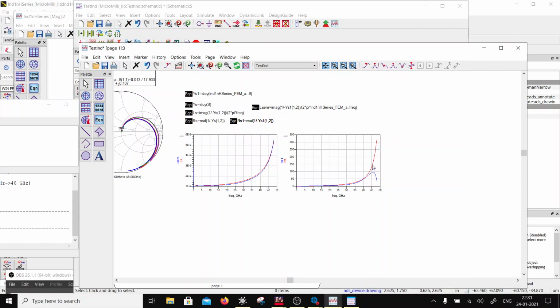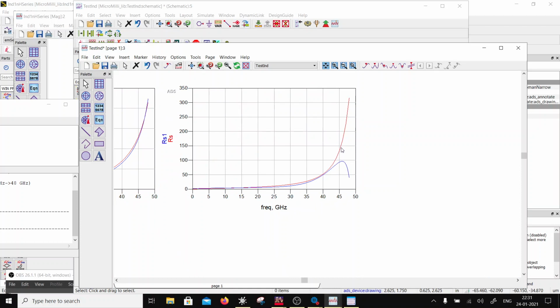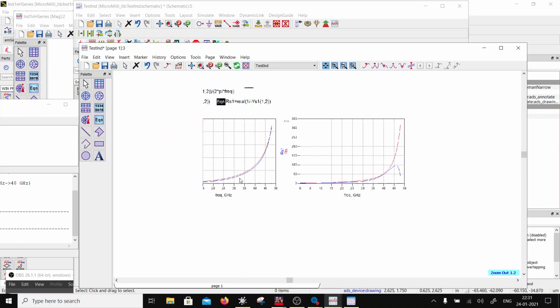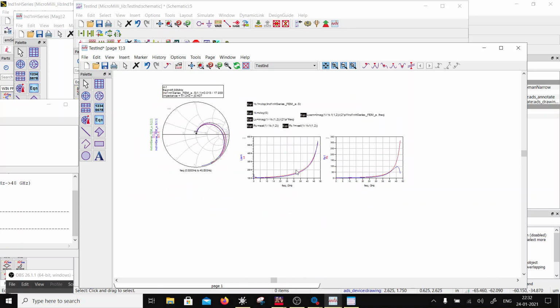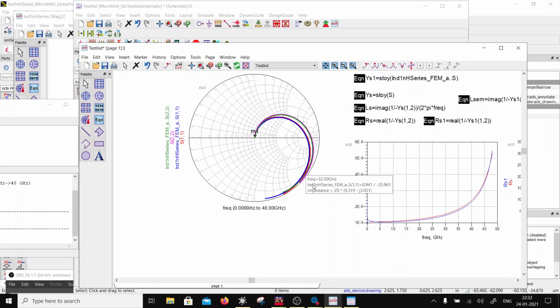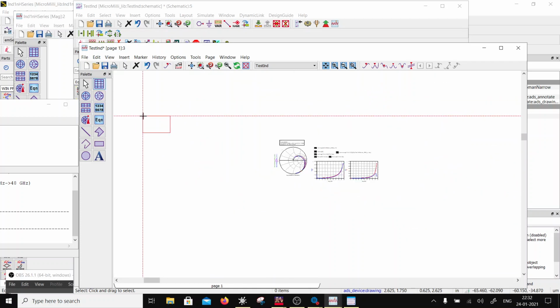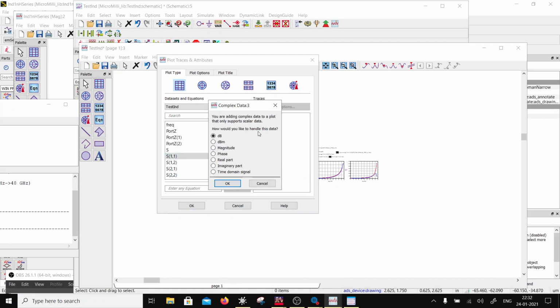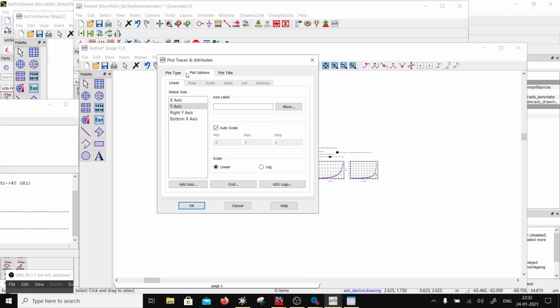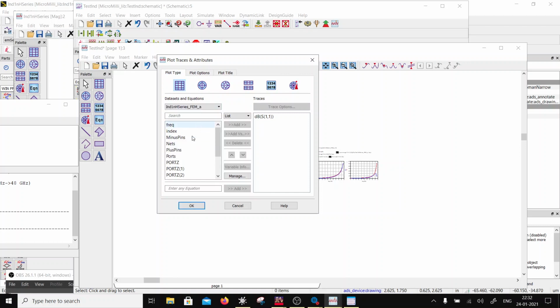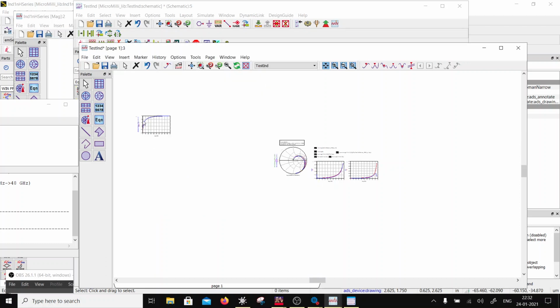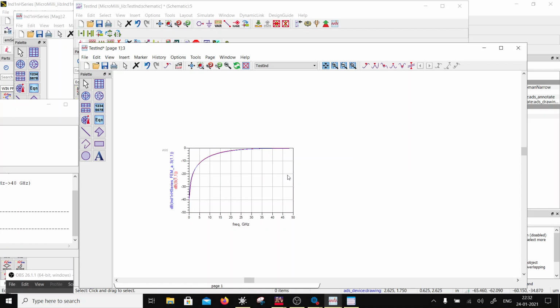Okay, so up to here it is going to 150 ohm and this is going to be 100 ohm. So there has to be a correction over here somewhere, right? There has to be a correction over here, right? So I'm going to leave it at that because I'm okay in this range where I want to model this, right? So let's look at S11 here in dB, and let's look at the S11 from the EM simulation in dB, and let's see how bad that is. So it's not bad, it's fine.